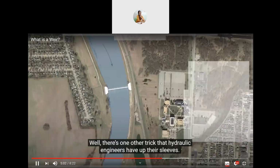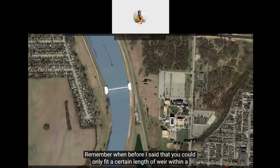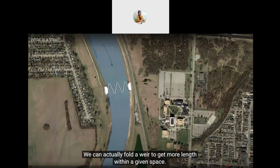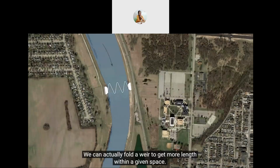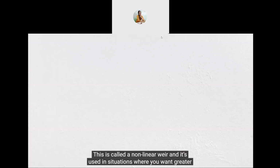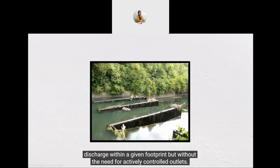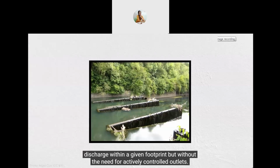Remember when before I said you could only fit a certain length of weir within a fixed footprint? That's not completely true. We can actually fold a weir to get more length within a given space. This is called a non-linear weir, and it's used in situations where you want greater discharge within a given footprint, but without the need for actively controlled outlets.